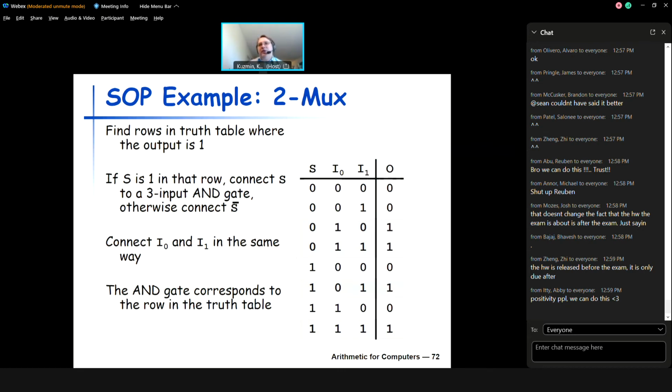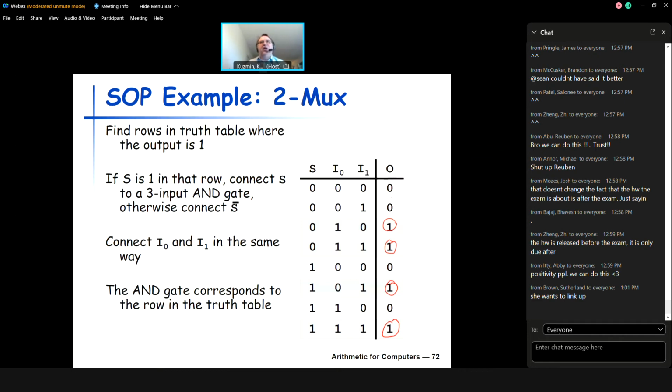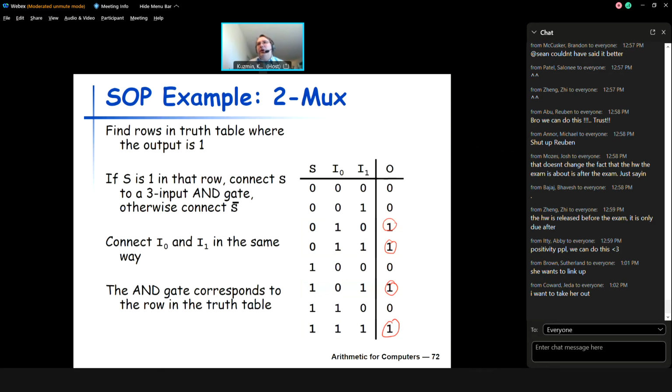So imagine you are given a function with this kind of truth table. We are trying to construct the circuitry that would implement this truth table. Intuitively, hopefully it's clear that we just have to make sure that our circuit produces ones for those rows where we have ones. And that would mean that for all other combinations of inputs, it would produce 0, because we only have two values, zeros and ones. So whenever the output of our circuit is not 1, it invariably will be 0. So we don't have to worry about zeros, we have to worry about ones. We make sure that when our function is 1, our circuit produces ones, and all other combinations will be zeros.